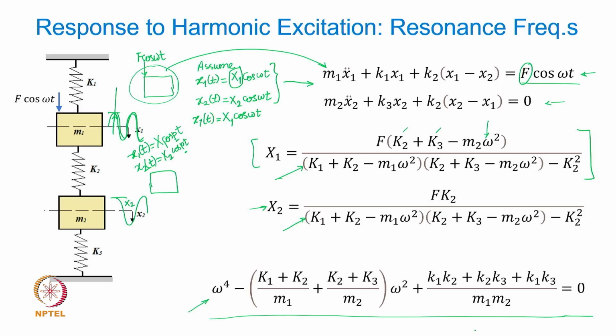So it actually means that this equation will give you two values of the frequency, in this case the forcing frequency, where amplitudes will reach infinite value. And from the single degree of freedom system case, you already know what that is called: resonance. When the value of omega 1 is equal to the natural frequency, you will have resonance.